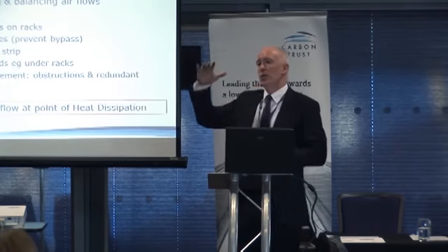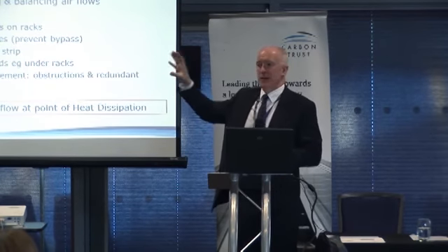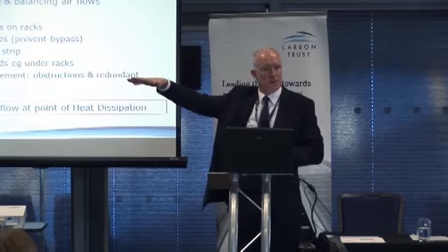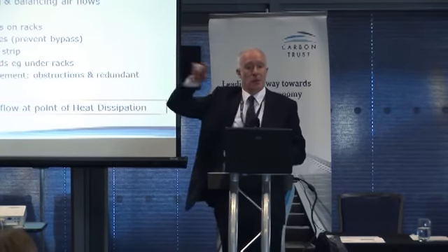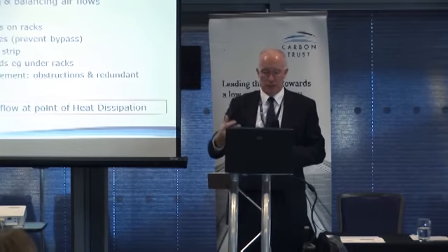If you've got a rack with a number of computers in it, you may have blank spaces. And if you have those blank spaces, the air will go through the blank spaces. It won't go through the fanned computers so much. So let's just put, for £5, blanking plates so that all of the cold air that's valuable is forced through the computers. It's there, it's ready to go.